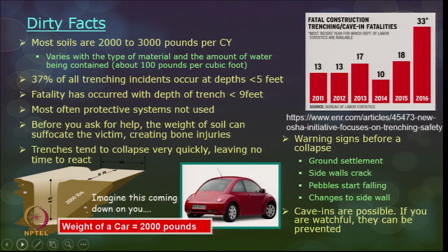Now, let us see what these cave-in fatalities are and some statistics on what cave-ins are all about. Some dirt facts, because soil is considered to be dirty. Most soil is very heavy. Soil is not lightweight. Statistics say 1 cubic yard of soil weighs around 2000 to 3000 pounds. So, 1 cubic foot of soil weighs more than 100 pounds.